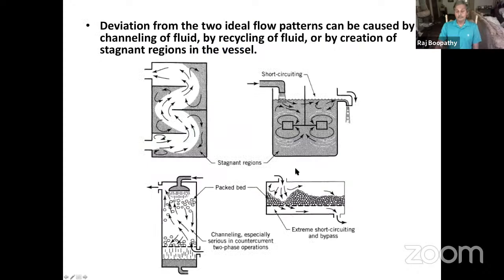And this is called, they put a baffle in there, so you have a partial mixing, we call arbitrary flow. So here you don't have to have a mixing device. So the wastewater comes and hits this baffle, and it creates a partial mixing without using energy to mix it. And we call it an arbitrary flow reactor. So now I'm going to show you some of those reactors. All of them follow one of these principal types of reactor.